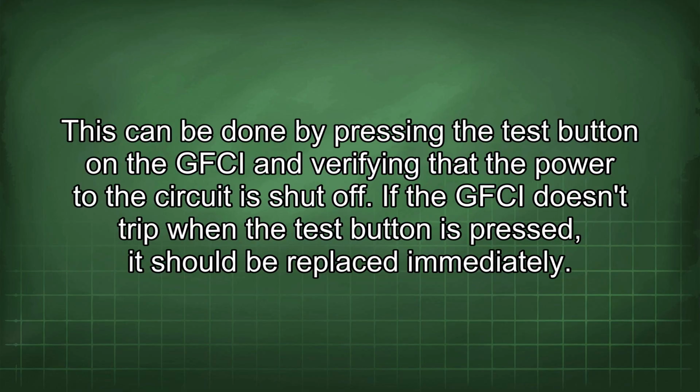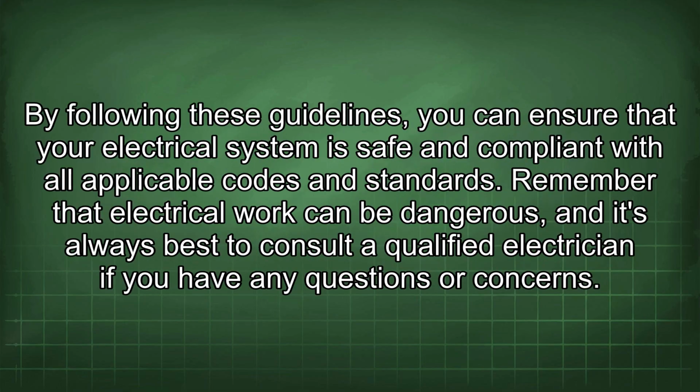This can be done by pressing the test button on the GFCI and verifying that the power to the circuit is shut off. If the GFCI doesn't trip when the test button is pressed, it should be replaced immediately. By following these guidelines, you can ensure that your electrical system is safe and compliant with all applicable codes and standards. Remember that electrical work can be dangerous, and it's always best to consult a qualified electrician if you have any questions or concerns.